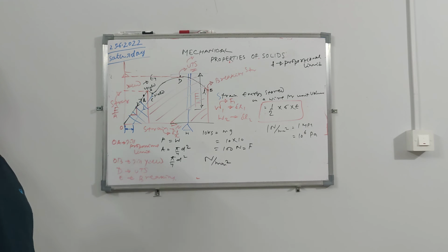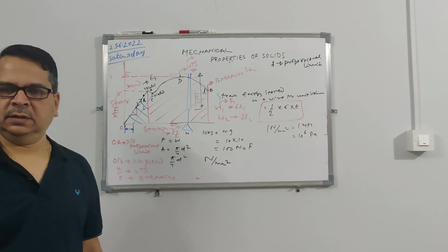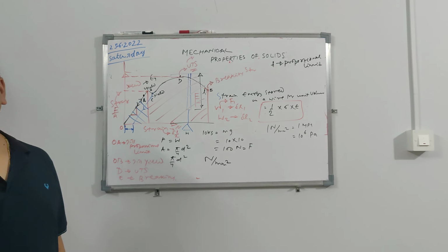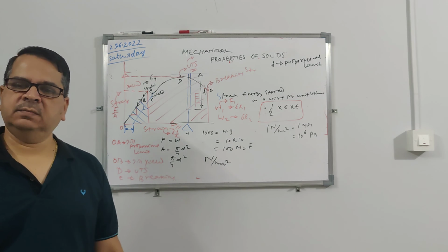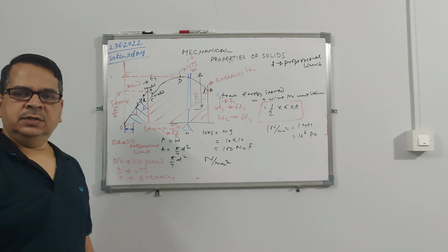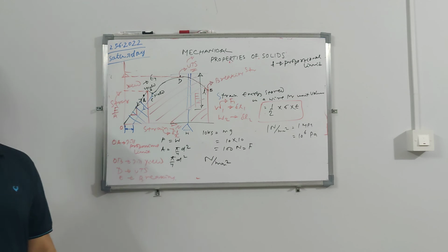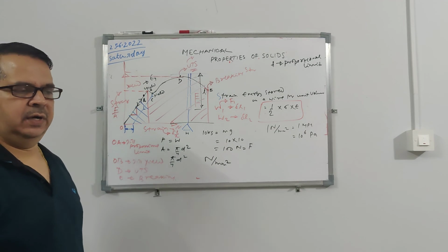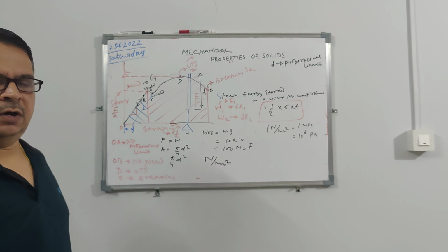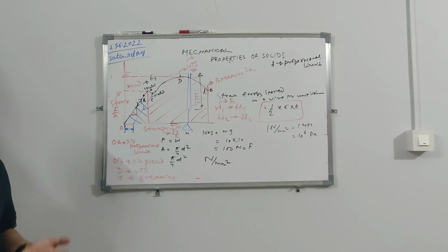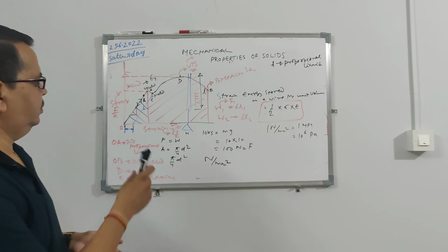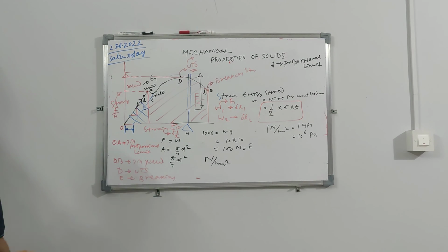But for some high stress components, like gas turbine engines, when the temperature is very high and it is rotating at some 10,000, 12,000 RPM with very high centrifugal force, it may go into plasticity. But for ground-based structures we don't allow that, because you don't want the structure to have a permanent set. It should operate within the elastic region.